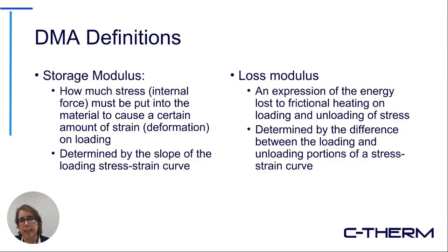There are two key moduluses that we talk about when we're talking about the mechanical properties of polymers. The first one is the storage modulus, which is roughly defined as how much stress, or so-called internal force, has to be put into the material to cause a certain amount of deformation or strain when you're loading the polymer sample with strain.